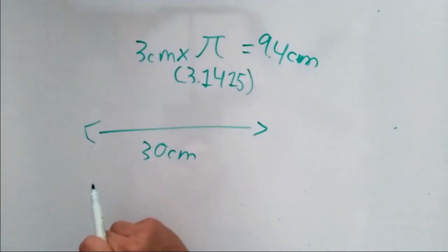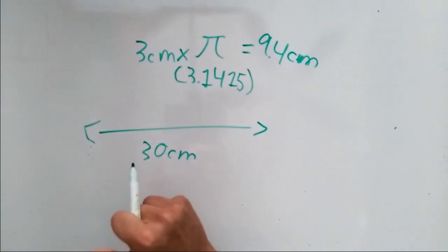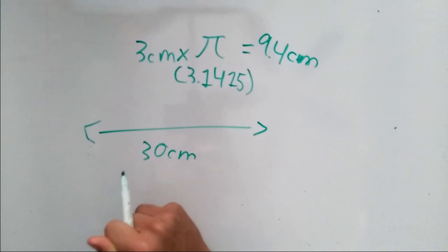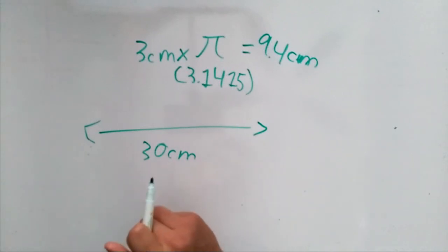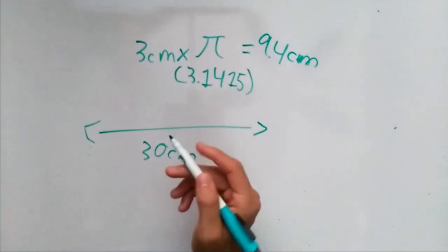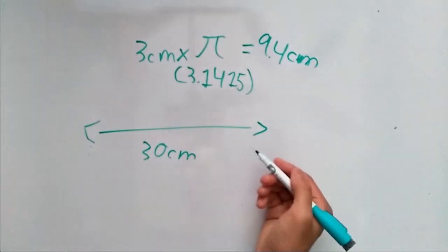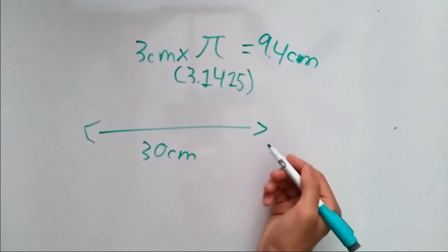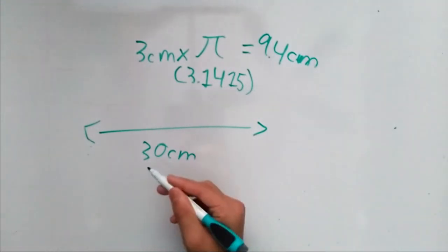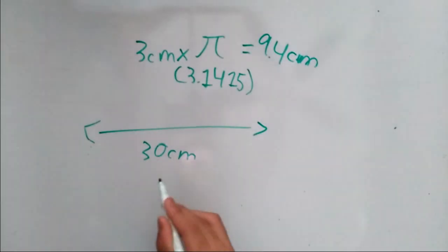But here's the problem with that. We still forgot one last thing. Most people use degrees instead of rotations, at least at FLL competitions. And the reason for that is there's a much higher resolution. You have 360 degrees in a rotation, so you have 360 times the resolution. So in order to get the result in degrees, we need to multiply this entire thing by 360.